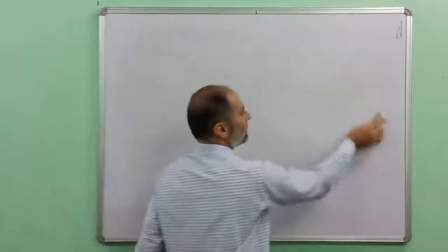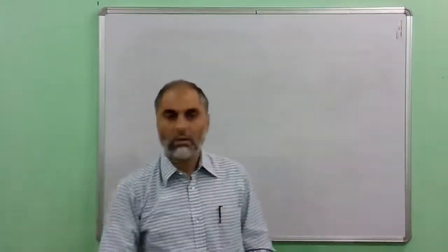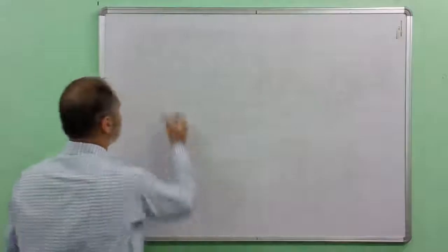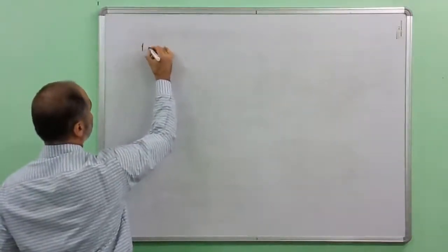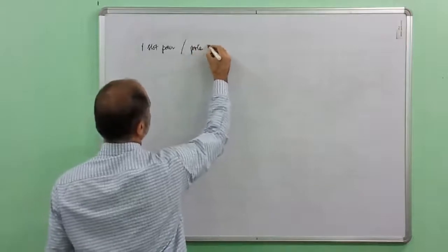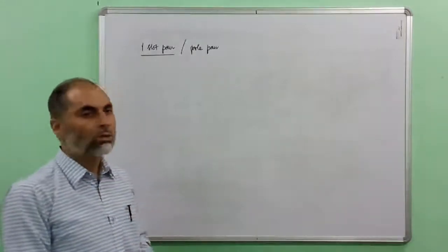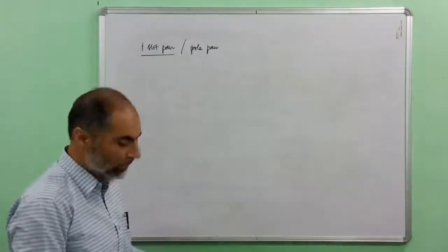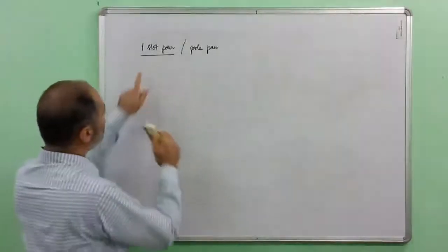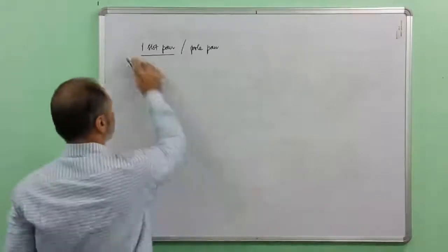So we have seen that by providing a single coil in a single slot pair, there are two poles created on the stator. So we have a single slot pair, one slot pair per pole pair. This is the minimum number of slots required. We require one slot pair to create one pole pair. Now let's see how four poles can be created on the stator. Therefore, we can easily see that to create two pole pairs, we'll at least require two slot pairs.